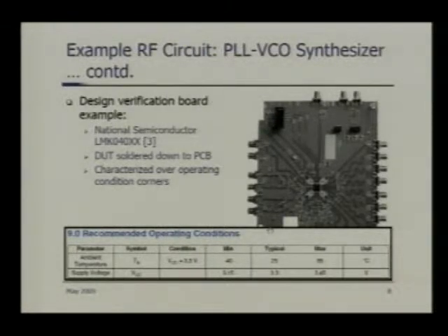But there is a performance issue as well. If you are using a contactor, the inductance and the parasitic capacitance of the contactor or socket will come into play. That may degrade the circuit specification, for example the RF output power level that we discussed, which the real life application may not see at all.